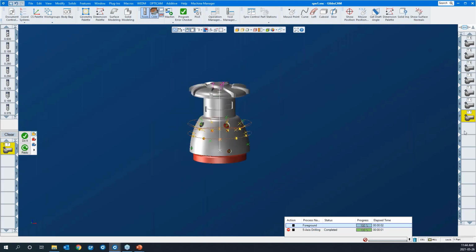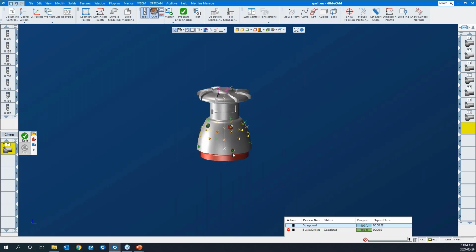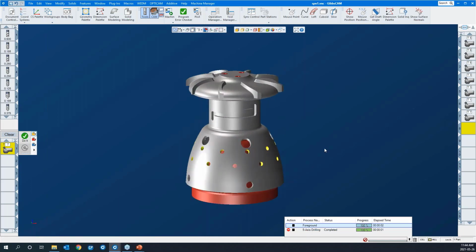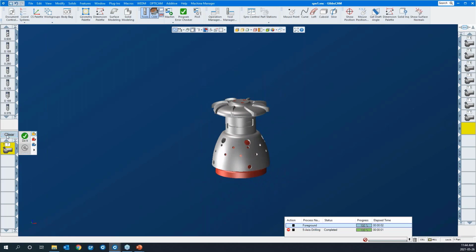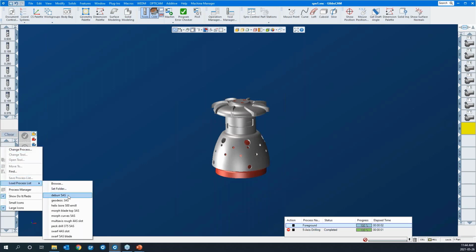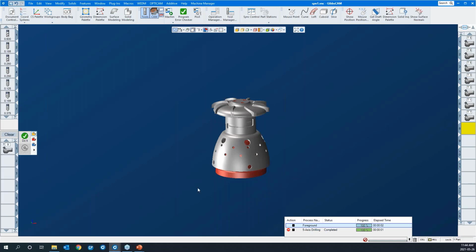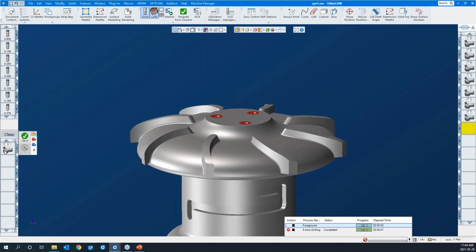Okay, there's a couple other toolpaths I'd like to show you. If you want, you'll keep these hole features, but along the floating taskbar, you can just turn them off so that they're not visible. There's 5-axis deburring, automatic 5-axis deburring in the 5-axis module. Let's just have a look at that. I can pick the entire solid and have it go at it and then exclude edges or what have you. But what I've done is I've created a feature that defines the blades. And we'll have a look at that.